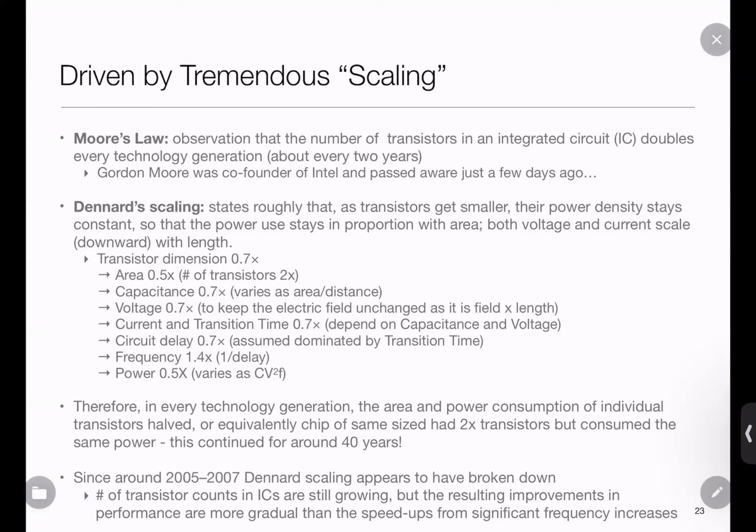The fundamental bottleneck is, I have a piece of silicon, how tiny a transistor can I draw on it? And we draw it using light. In effect, we create a mask through which we shine light, and when that light falls on the piece of silicon, which has some other chemicals on it, it results in transistors being formed. So originally the thought was, I cannot draw something finer than the wavelength of that light.